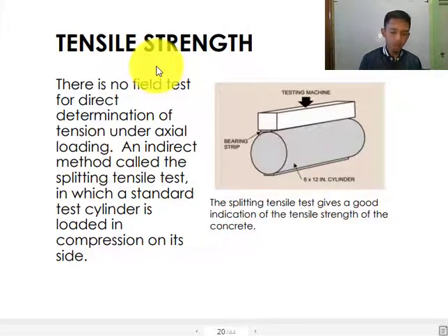That's why we have what we call reinforcement. That's why we add steel to it, because the material that has high tensile strength is metal. That's why you have the subject reinforced concrete. It means that we add metal to the concrete so that it is strong in tensile, and of course the same thing with bending.